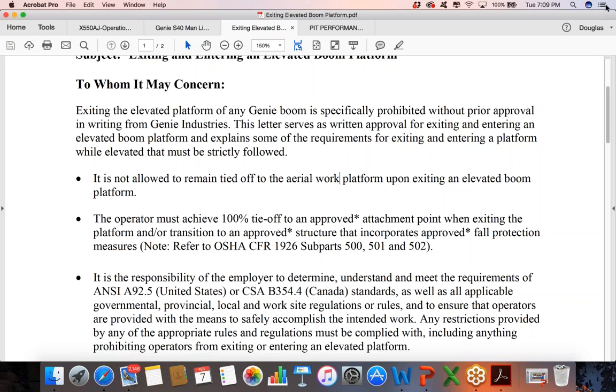And then last of all, we're looking at controlled decking zone. What are we talking about? We're talking about an area where there's going to be certain work. There's going to be initial installations and placement of metal decking where there are going to be a lot of leading edges where employees may fall, because we're putting decking on, so there's going to constantly be open edges. And also, where it may take place without the use of guardrail systems.